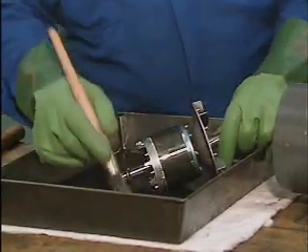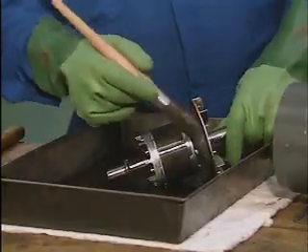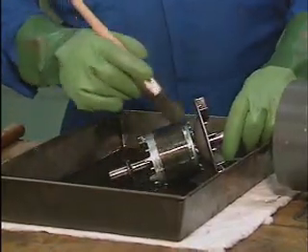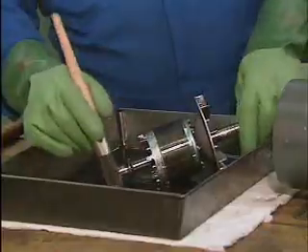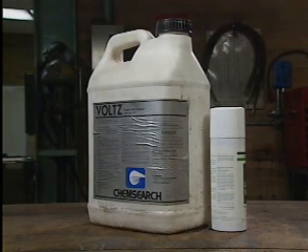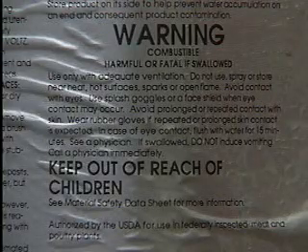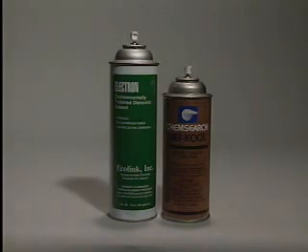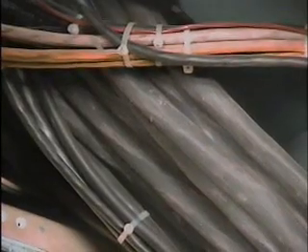Another chemical hazard associated with electrical maintenance involves the solvents that are used to clean equipment, such as motors. Many solvents are skin and eye irritants. Some can also be poisonous when they're ingested or absorbed through the skin. Solvents in spray or aerosol form can be dangerous in another way. Small aerosol particles or solvent vapors can mix with oxygen in the air to form a combustible mixture.